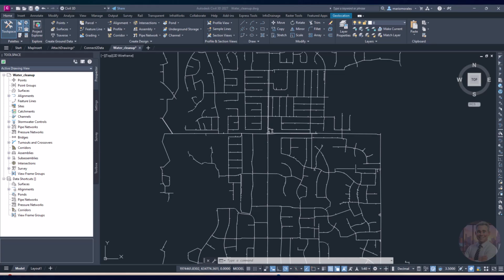So when you launch Civil 3D, you actually have all three programs running simultaneously. And you can switch to the various workspaces to focus on any one of those dedicated products, or you can launch any command from any workspace. So I can be in Civil 3D, launch a map command, be in map, launch a CAD command, on and on. So just be aware of that. If you have Civil 3D, you have Map 3D.